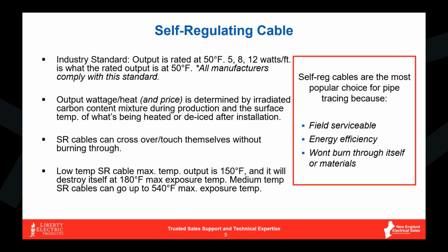And what really defines low temp is that it's at an operating exposure temperature of 150 degrees or below. This cable will start to destroy itself around 180 F. So, henceforth, that's always been a great standard to use for things like asphalt shingles when you're doing roof and gutter de-icing, or PVC, CPVC piping when we're doing pipe tracing, because again, that's well below the melt points of either of those materials or any sort of an ignition temperature set point. So again, very, very popular.